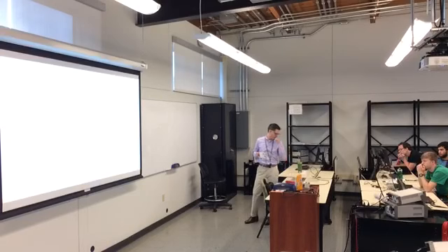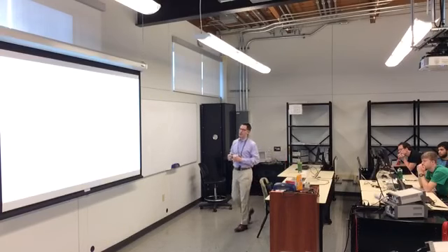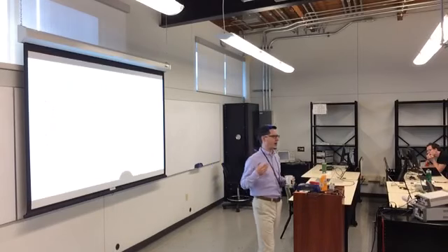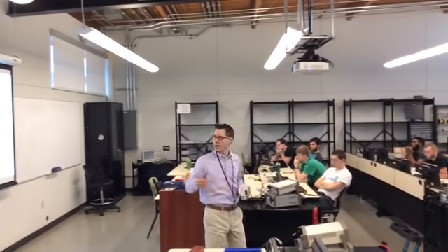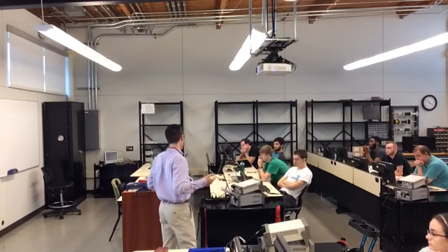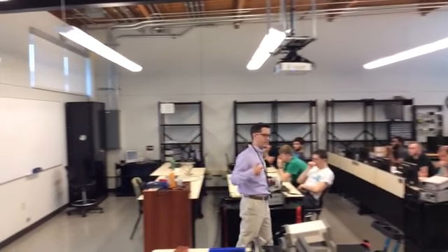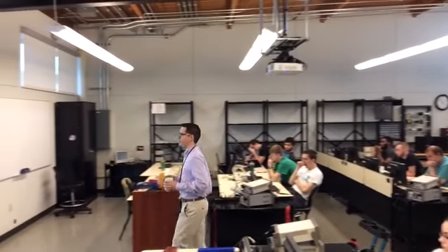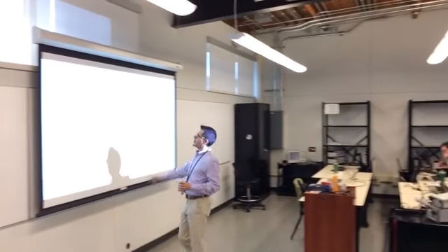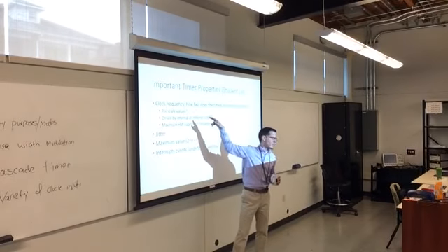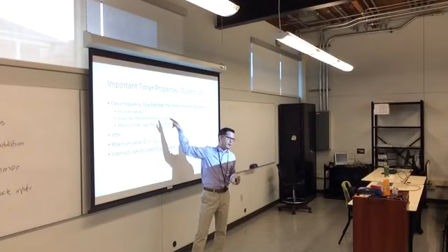So some things to consider when you're talking about a timer and you're trying to pick how do I use it, what properties do I need, is what clock sources does it have? What modes can it be in? How many different places can I drive that timer from? If I have a really fast clock, can I scale it down? Can my timer be driven by an external clock? Or does it have to be an internal clock?